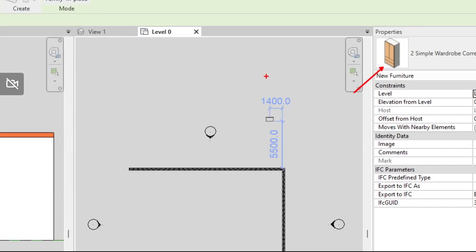So this rule of building your elements front to back will be true for most of the Revit family templates that you work with. Of course, it's always a good idea when you start off a new family, if you're using one of the more specialized versions, to do a quick test. Do a simple extrusion, see where things are lining up, load it into the project and test it. Just make sure that the preview you're getting here is going to be a useful one. There we are.